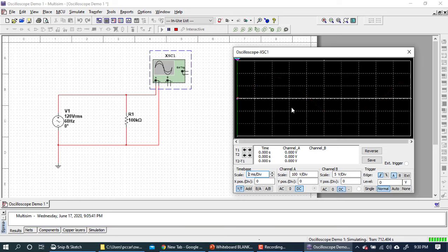Inverse of time. So 16.666666, hit the 1 over X key, and I get 60 hertz. And don't forget that's in milliseconds. So when you put that in your calculator, you're not entering seconds. Don't put in 16.66666 seconds. It's milliseconds. So you have to convert that to seconds, which is what? 0.0166666666. Or you can put in 16.66667 times 10 to the negative 3. You can do that as well.